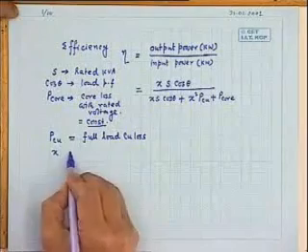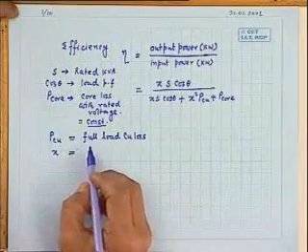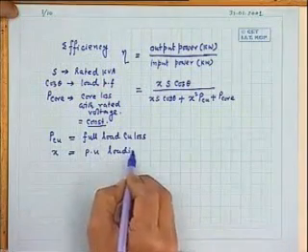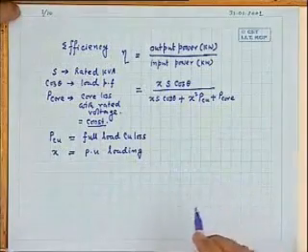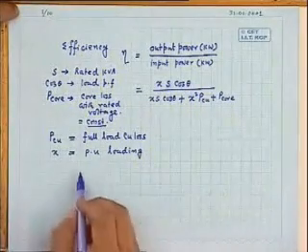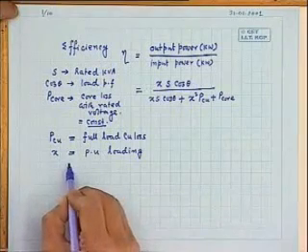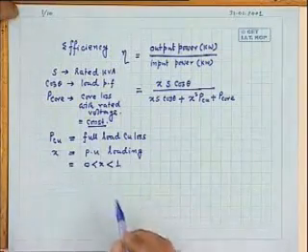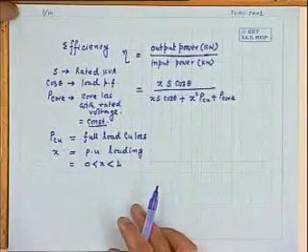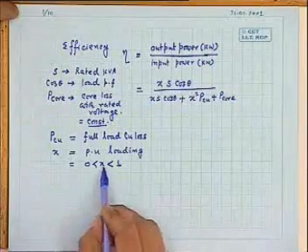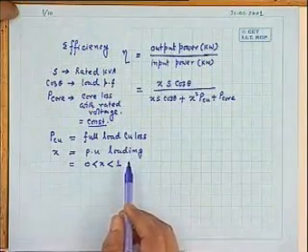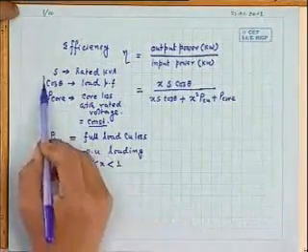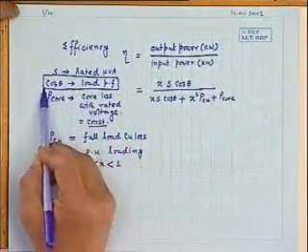And X is the per unit loading or fraction of loading. X is the per unit loading of the transformer. Or sometimes you can call it also degree of loading of the transformer. It will be generally a fraction lying between 0 to 1. The value of X equal to 0 indicates that the loading is 0, output power delivered is 0, and when X equal to 1, the kVA handled by the transformer will be S kVA. And cosine theta is the power factor of the load.